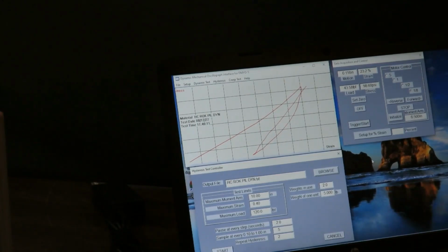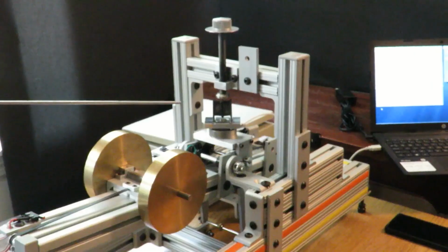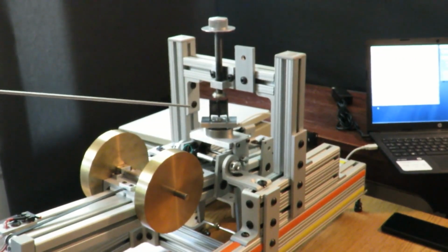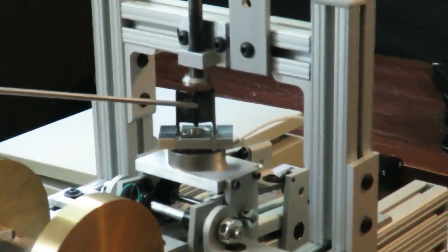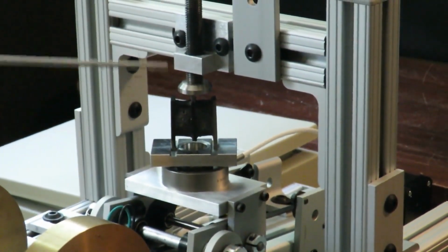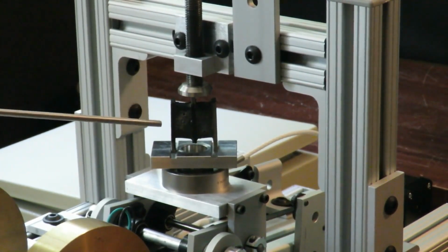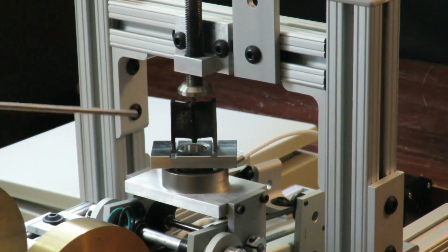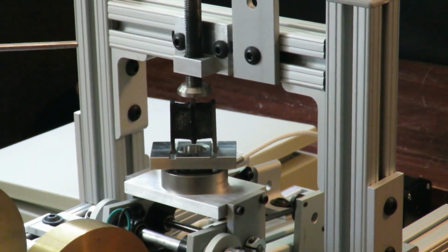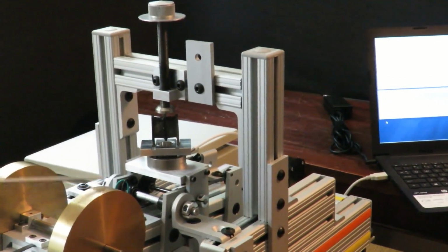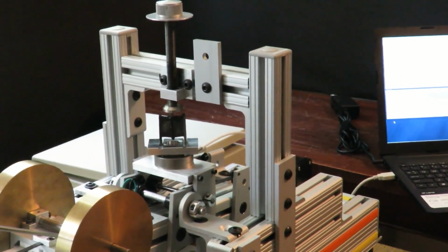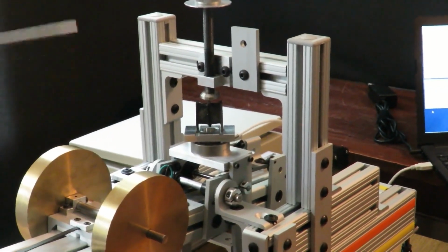However, we also have the shear tests. The shear specimen is composed of two rubber components bonded to three steel platens, and the forces are perpendicular to the beam. So in this case we have a shear specimen which we will run a dynamic test on, and as we can see there are two weights on the traveling table, and that is ready to run now.